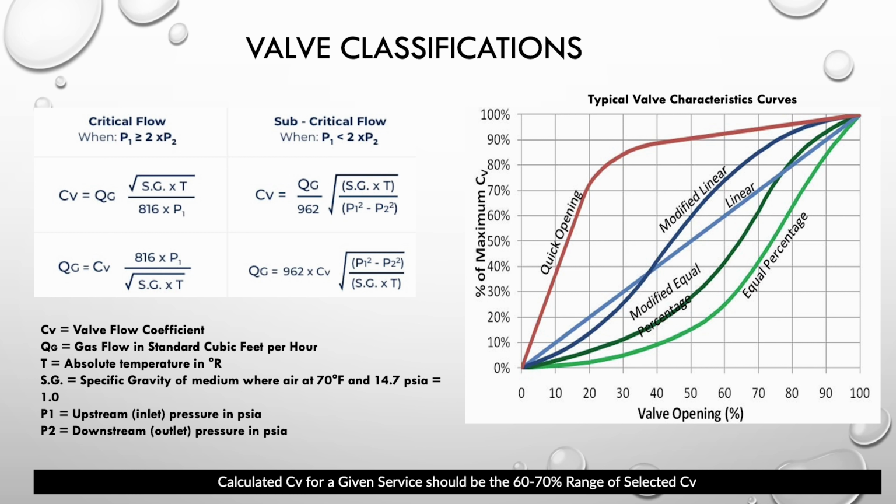Now, if you have a process where you want to regulate, for example, pressure, and that pressure impacts the process significantly, you want that pressure to move as slowly as possible. You want tight, slow control, because you want tight control. So normally you're going to be using the equal percentage. That is very cool.